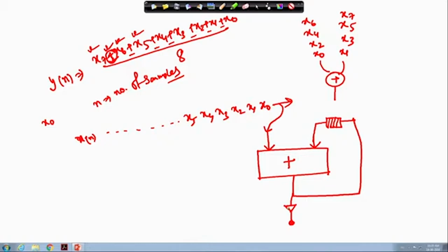That means this is the condition where the execution of the loop will be over and the corresponding results will go to the output bus. So, I need one output enable signal that indicates that the required number of samples has been consumed. Now, produce the result to the output.